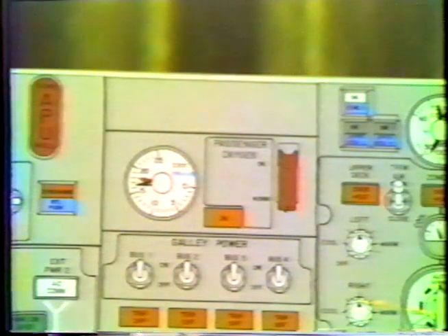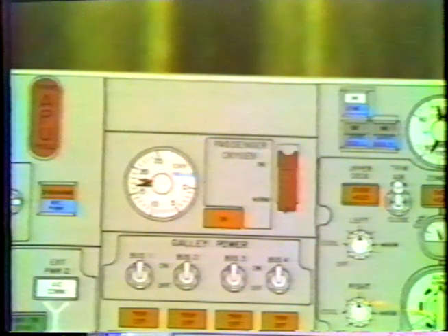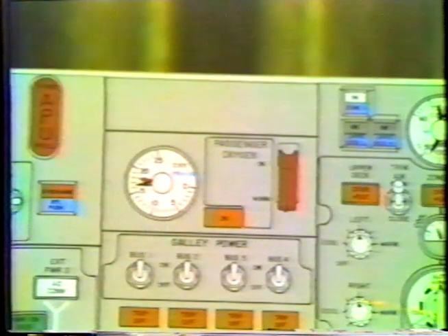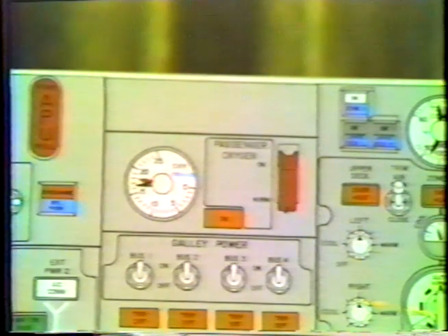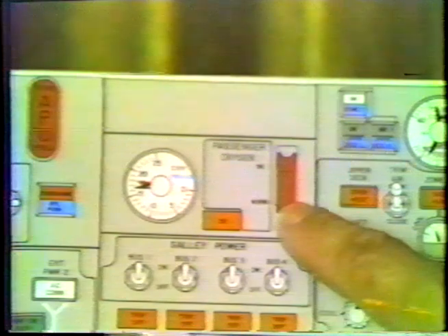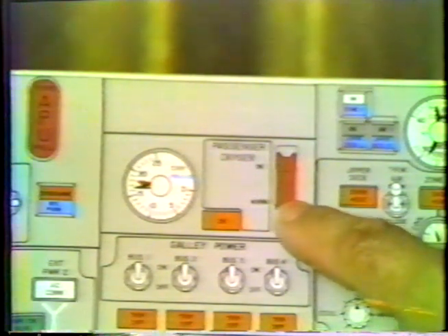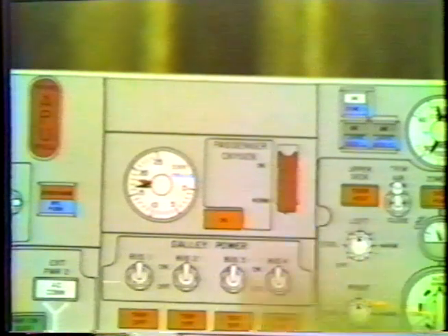The system is pressurized by one of two methods. Normally, it is used in case of an emergency when the cabin pressure is lost, and if the cabin altitude goes above 14,000 feet, it's automatically displayed. However, at any time below 14,000, if it's desired to present the mask to the passengers, a switch here can be operated that will electrically display the mask and pressurize the system.